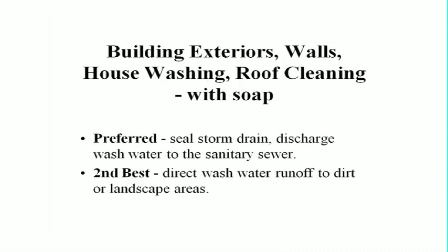Building exteriors, walls, house washing, cleaning without soap. Preferred: seal the storm drain and discharge water to the sanitary sewer. Second best is to direct the wastewater runoff to a dirt or landscaped area.